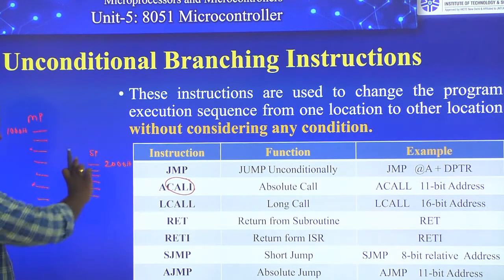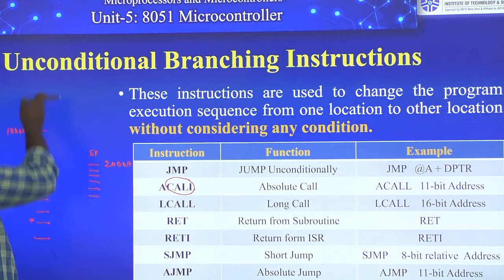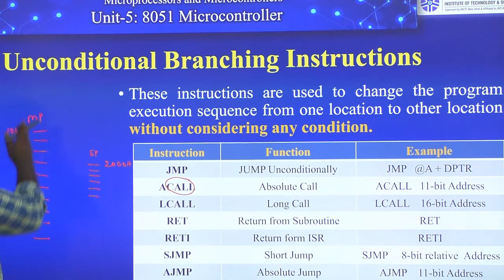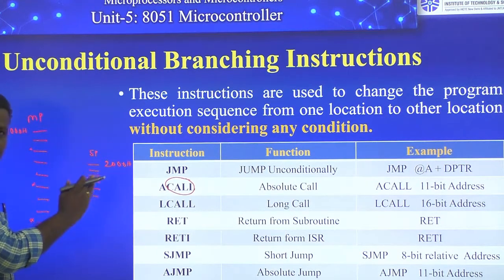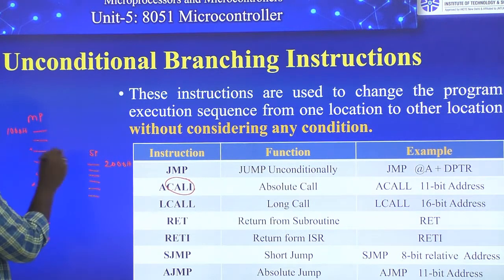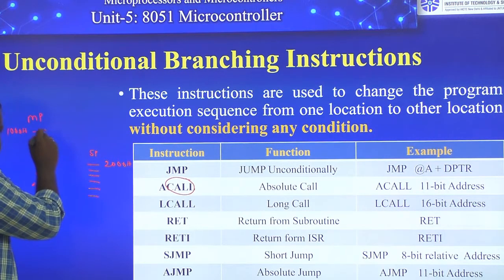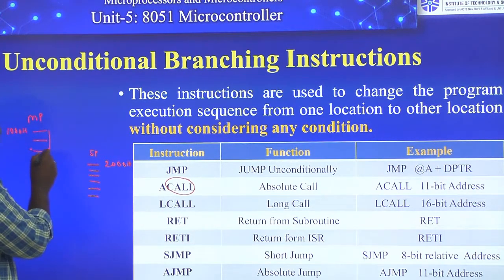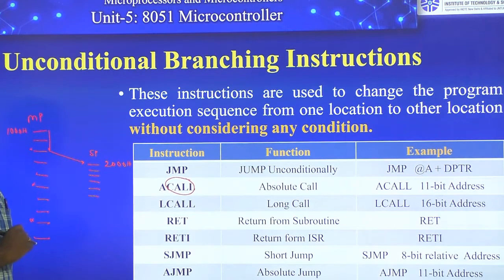If I write it out here each time, the total size of the main program increases. Once the main program size increases, it automatically occupies more memory. So to overcome that, we write our subprogram separately from the main program. Then wherever I want the subprogram, I can use a CALL instruction. By execution of that call, our execution is shifted to the subprogram.